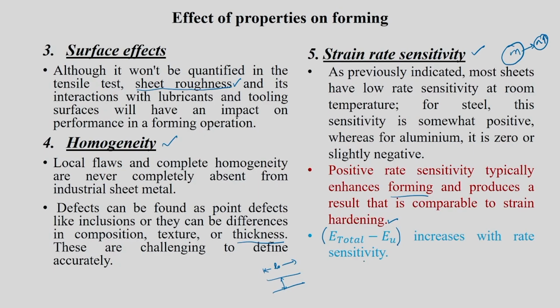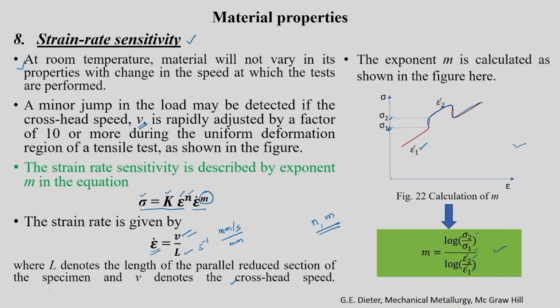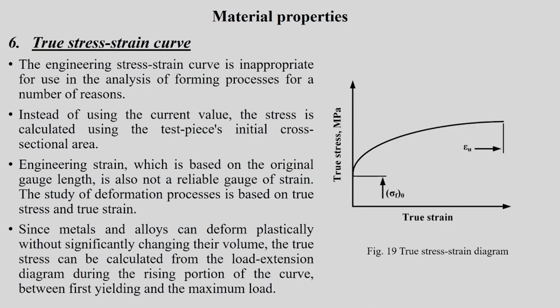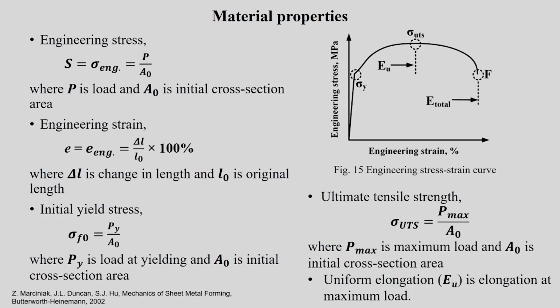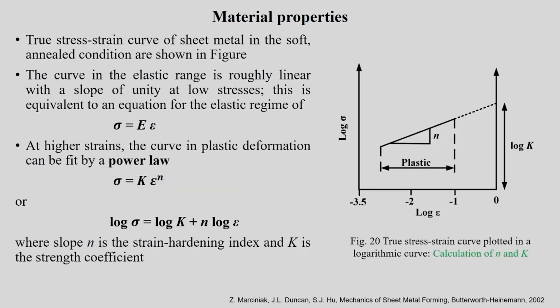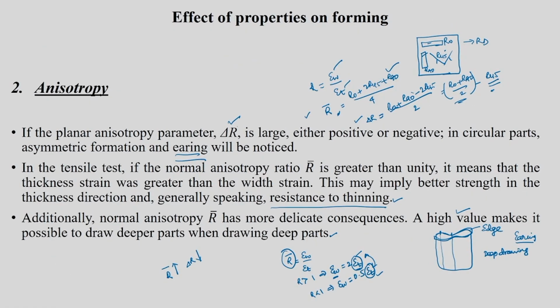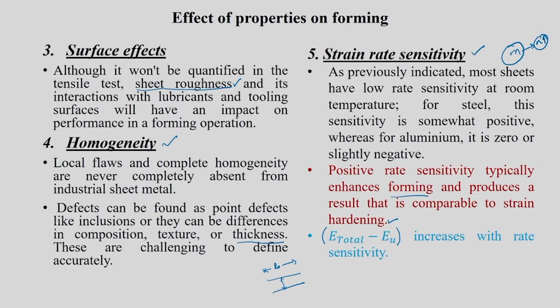Okay, what does it mean? It means that suppose you pick up a stress strain behavior, where we have seen that somewhere here. Suppose you take this particular engineering stress strain curve, for example. In this range, epsilon T minus epsilon U, this is actually controlled by M. Whereas before that, in the strain hardening region, N plays a vital role. Okay. That is the meaning.